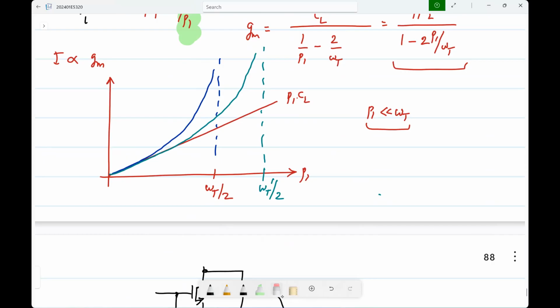This is why in many cases you will see this, and in digital circuits, it is the same thing. When you see a terabit per second or 100 gigabit per second data path, it's not that you have a series of flip-flops clocking at 100 gigabits per second. There may be 64 parallel paths, each one operating at some 1.6 gigabits per second or even more. I mean 128 paths and so on. So the aggregate data rate will be something like that.